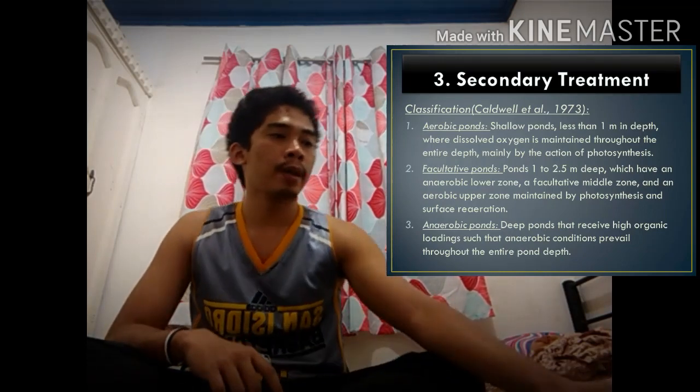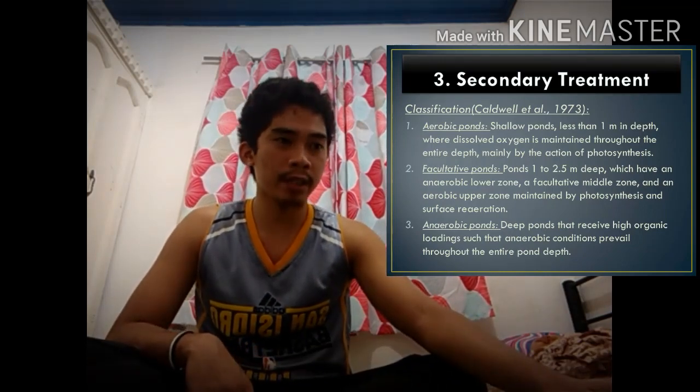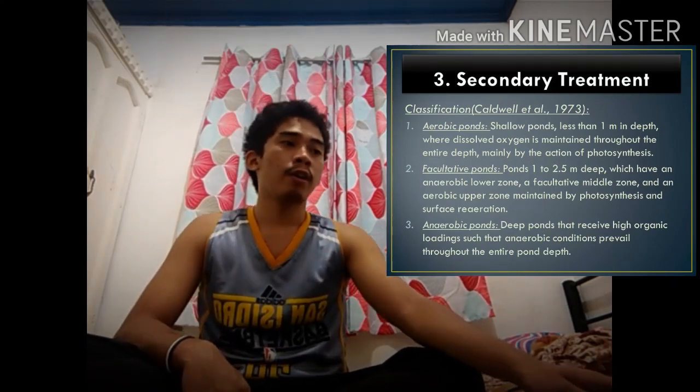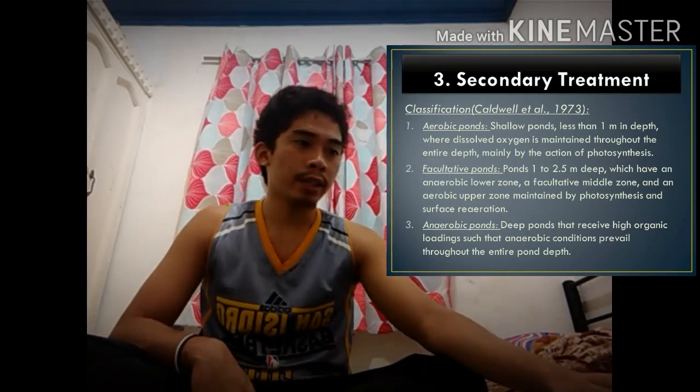The third classification is the anaerobic ponds. These are deep ponds that receive high organic loadings such that anaerobic conditions prevail throughout the entire pond depth. In this classification, the pond is very deep and receives high organic loadings such that anaerobic conditions prevail throughout the entire pond depth.